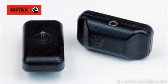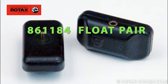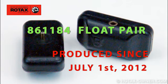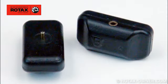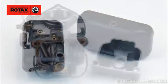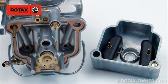Also affected are all floats with part number 861184, produced since July 1st, 2012, which have been installed as spare parts or installed during an engine repair or general overhaul. It's possible that the carburetor and/or the floats may have been removed from their original delivery engine and installed in a different one.